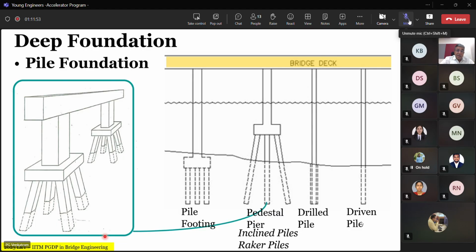When compared to vertical. Now, I didn't even ask that question. I said, what happens to the displacement under the action of a lateral load if the piles were only vertical and if the piles were raked? That was the question I asked. So for vertical piles, bending moment will be induced in the piles more, and for raker piles, it will be axial forces. I asked about displacement. You've gone towards the force.